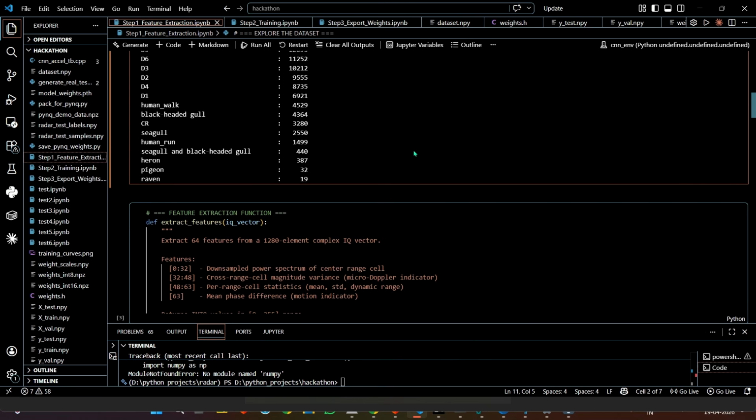The thing with the original paper is that we can't implement that in my PYNQ Z2. I'm using a PYNQ Z2 board, and it has 220 DSP slices. The number of DSP slices that are present in the PYNQ Z2 is 220. And if I were to physically implement the paper, then I would require around 1,000 DSPs, which is obviously impossible. So what I've done, I've scaled down the model from 2D CNN to a tiny 1D CNN with 3 convolution layers and 1 FC layer.